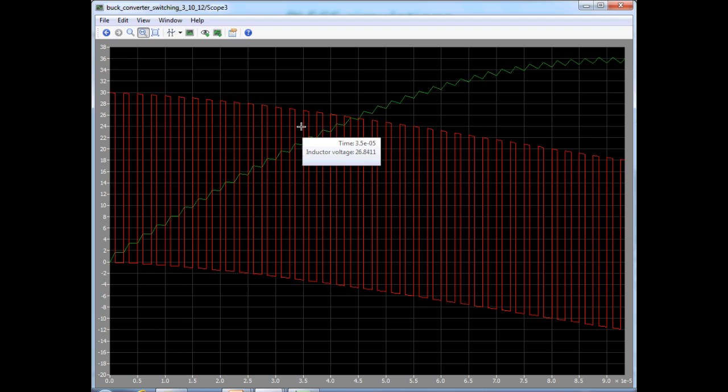That is because of the LC resonance. And the output voltage is also building up, even though it is not shown here. It can be inferred. Actually, the magnitude of the off state voltage is simply VO. It is minus VO, but its magnitude is equal to VO, and you can see it is clearly rising, going towards minus 12, or VO of plus 12.